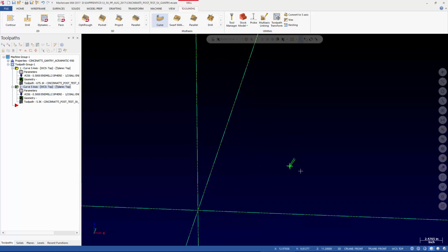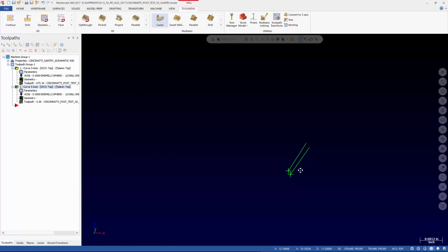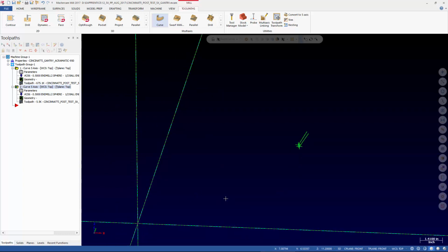So how does Mastercam take these relative tool positions and calculate the angles from them? We have to think in terms of our planes that we're setting up, right? The 2 vectors that are perpendicular to our axis of rotation. One of the things that we deal with internally inside the post is a bunch of mathematical functions that use vectors as their input.